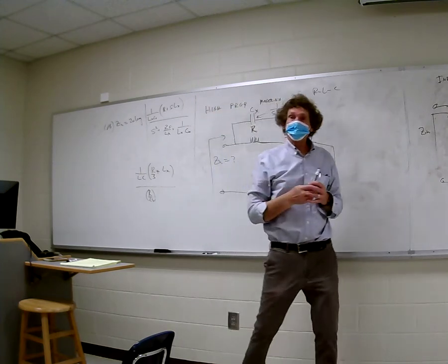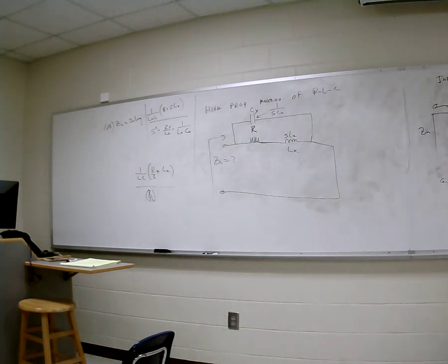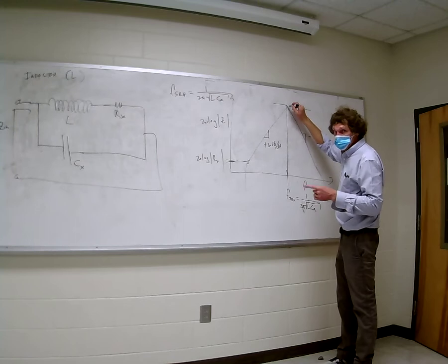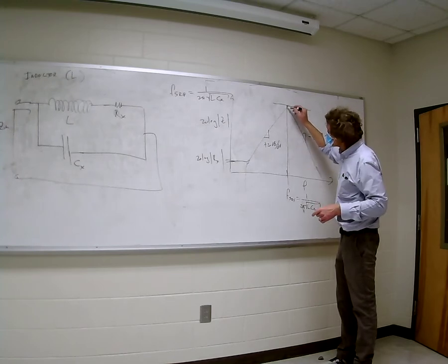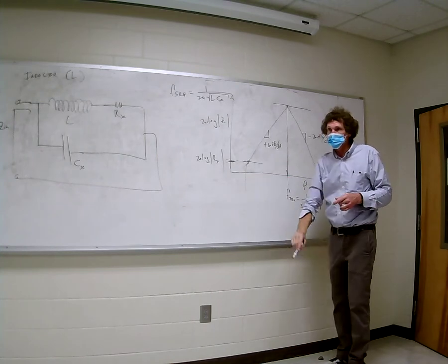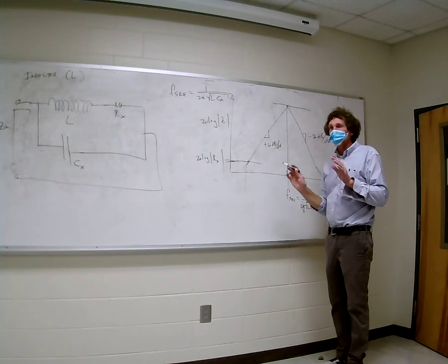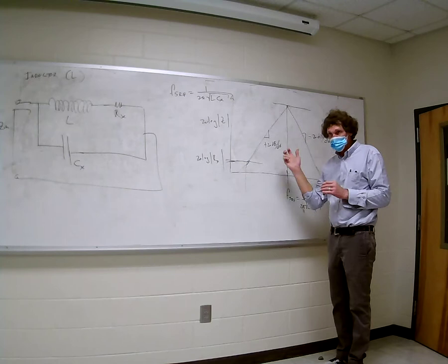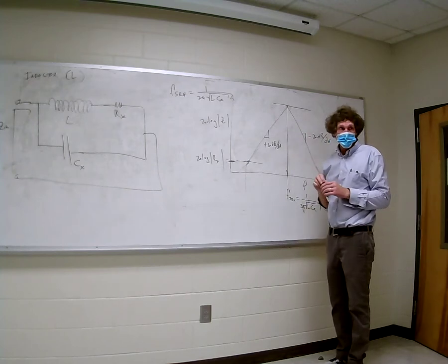Now that peak value is the only thing you worry about, because you know this is 20 times the log of Rx. And if I come from the peak value, which you just calculated, you can extrapolate it at 20 dB per decade to see where that line intersects that line. That's how you get that point. Don't worry about going through all the permutations of the equations. That's the easy way. Okay?